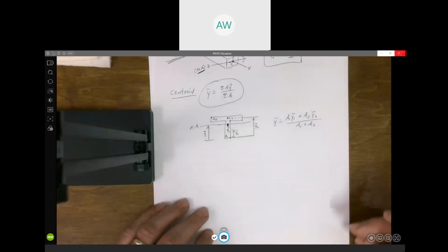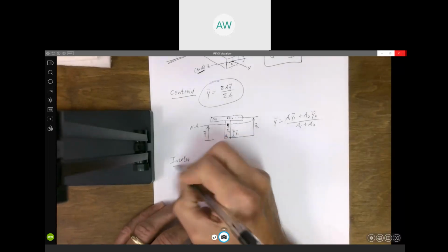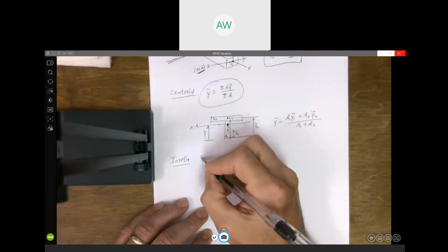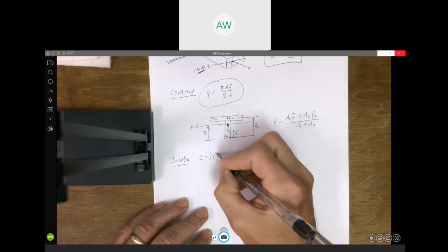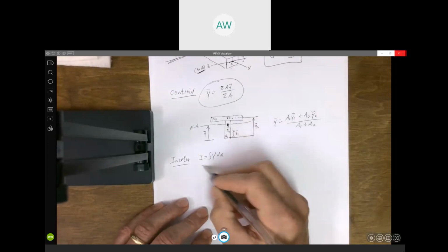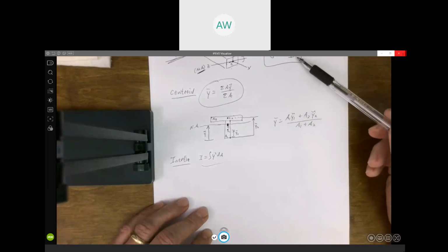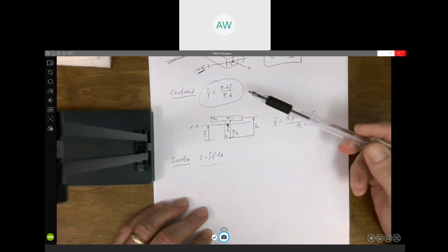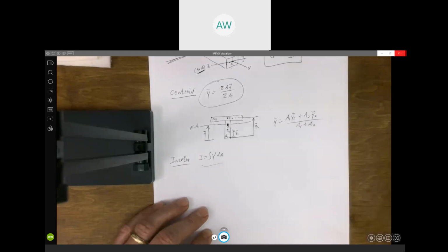So the other thing was we had to be able to calculate moments of inertia. Take a couple of minutes to talk about that. Now again, the integral definition is integral y squared dA, and we came up with that integral when we were deriving this formula. We replaced it with I. But as I said, with the centroids, we're not going to have to integrate anything.